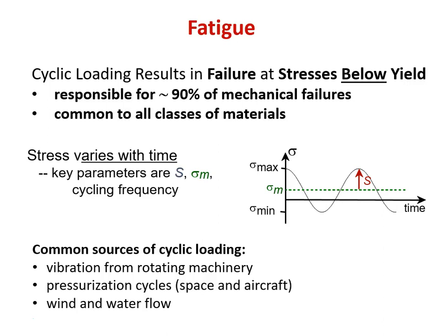So if you have a material with a yield strength of, say, 30 ksi, you can have a cyclic loading that varies between, say, 0 and 10 ksi, and have that drive a fatigue-related failure that can cause a low-rate crack propagation that will ultimately grow a crack to the size that it will exceed the K1C given your applied